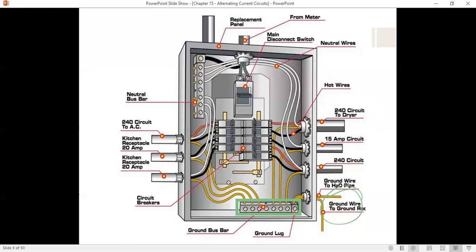Now, if this is your main breaker box, the main breaker box in the building, what they will oftentimes do is connect the ground to the neutral bus. In any system, you only want to do this once. The reason is that sometimes this panel will power another panel, which has its own circuit breakers. If we connect the ground and neutral in every circuit breaker box, you're going to have some of the ground wires, which aren't designed to do this, take back some of the power on the neutral. It's called bonding. You only want to bond one of these boxes.